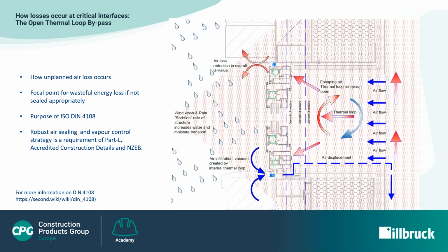We tend to forget that our buildings move and expand and contract, and inevitably some hidden, less obvious seals fail at the building connection joints. Nevertheless, let's take a look specifically at the window interface and see how these losses occur. Now, let's assume that our window has been sealed using more traditional methods, for example, a simple PU foam and an external silicone sealant. We know that traditional sealing methods are less efficient and begin to degrade over time, sometimes prematurely.